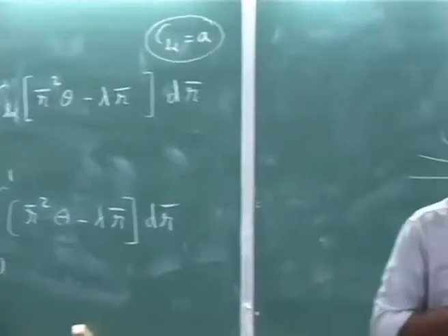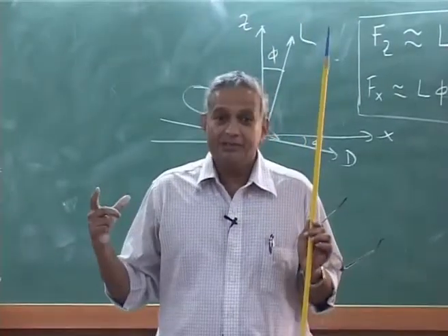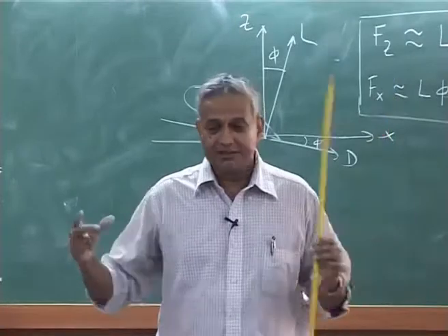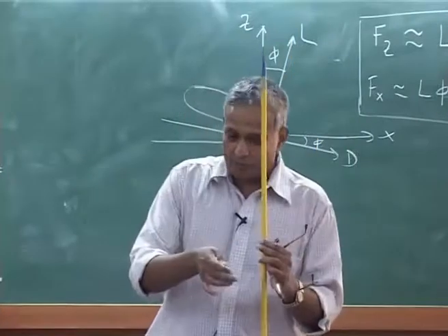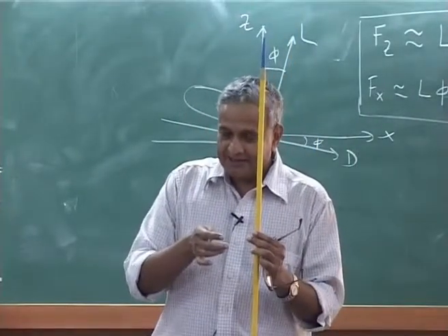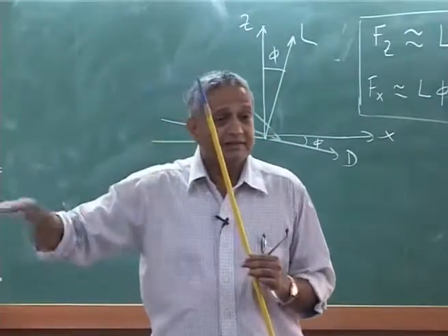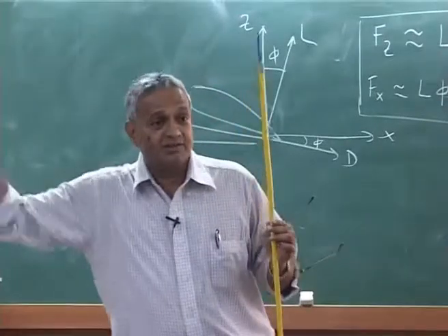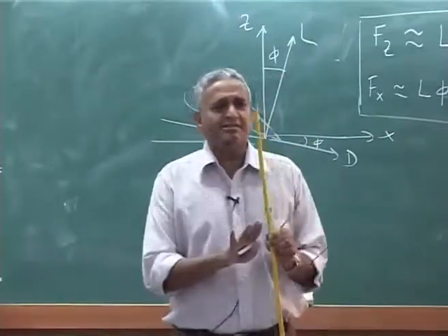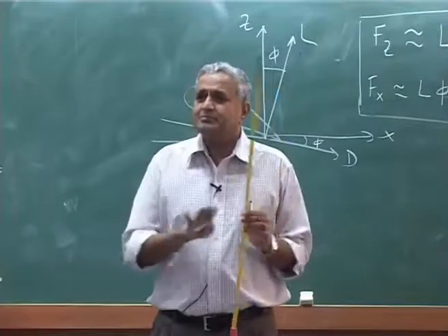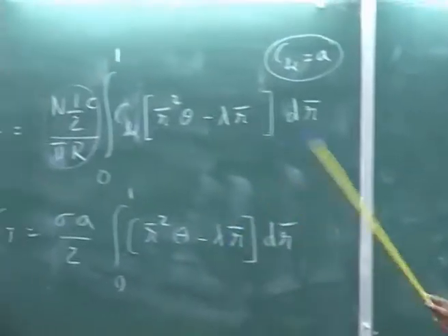I said the pilot gives an input, that is the pilot input he gives at the root, but the blade itself can be twisted. That means there can be a pre-twist in the blade, a geometric twist. That means what initially the pilot gives, and then what is the pitch angle at every cross section of the blade, that you have to take. Now, here, if it is constant, constant means there is no twist, zero twist. Zero twist means you can directly take it.